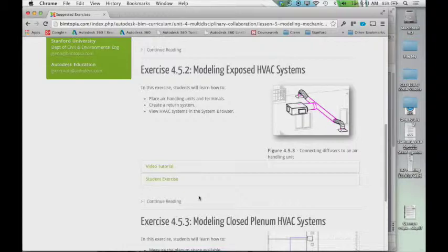In an open duct system, they'll often have some ducts that go out to parts of the restaurant to make sure they're pulling air from those specific spots, because even though it's open ducting, you still want to make sure the air's flowing. So it really just means there's no closed ceiling. Exactly, so you can see all that. That's why they tend to be these round ducts, which are kind of groovy architecturally, but a little bit more expensive to run. But actually very efficient, because round ducts are very efficient.